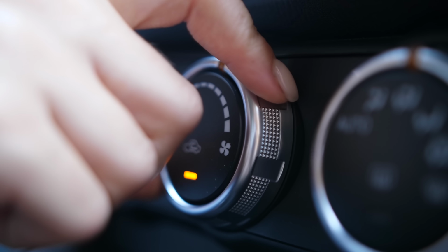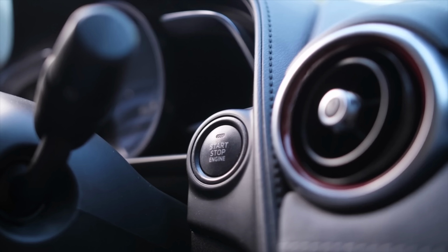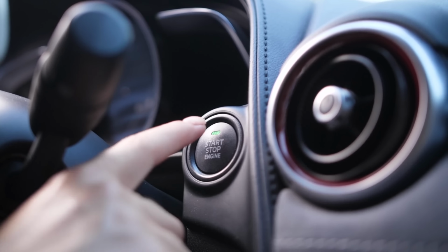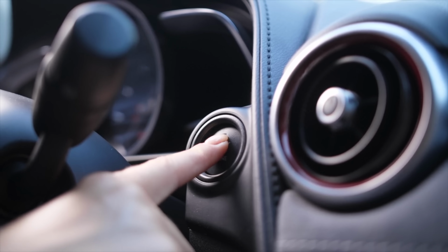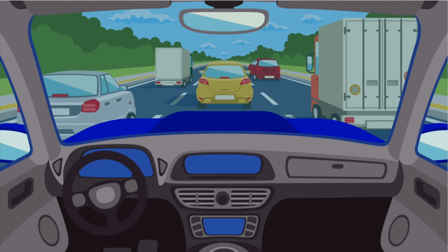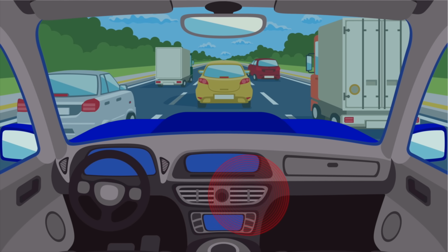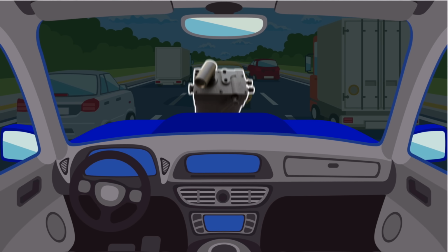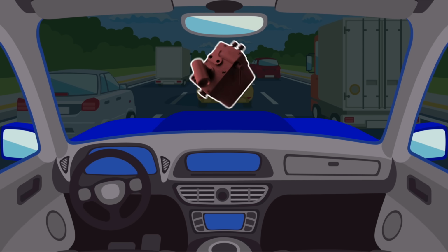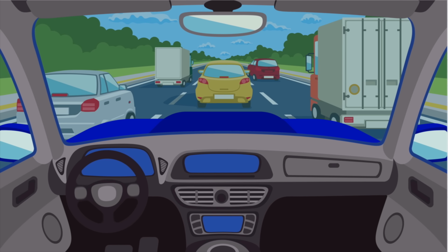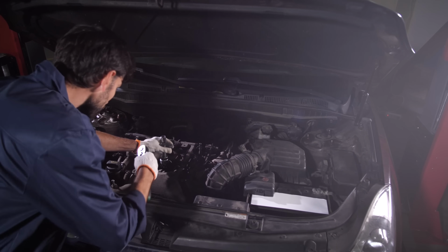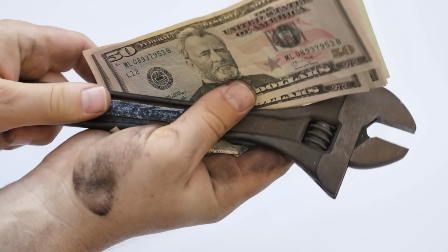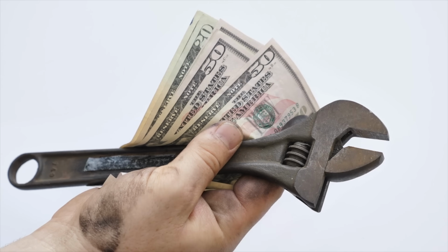Another sign your AC unit is failing is if the temperature of the cool air is inconsistent. This too can be due to a faulty or damaged evaporator. If you hear a high-pitched noise coming from your AC, that may be a sign that the pressure switch or sensor is failing. The switch can rattle against various parts of the engine compartment, so it's best to check this before any parts get damaged.